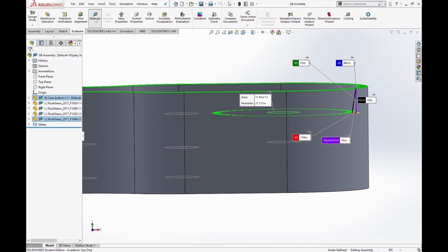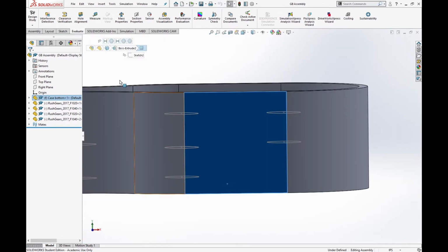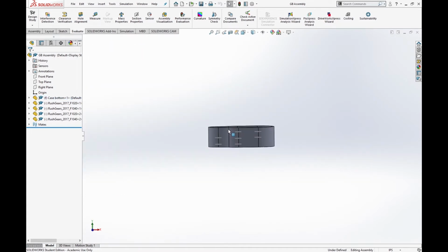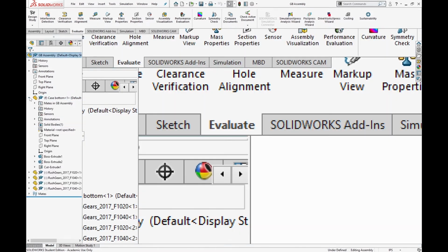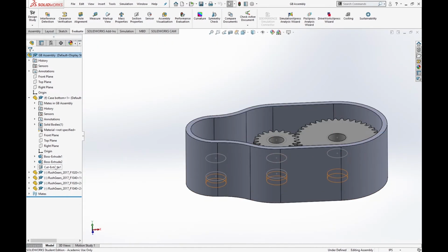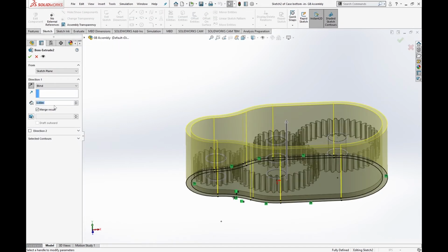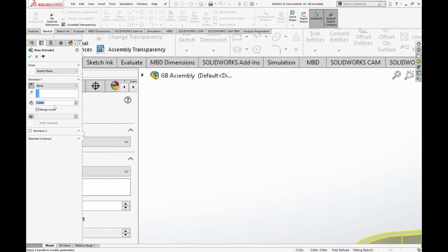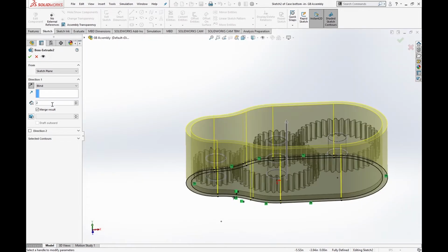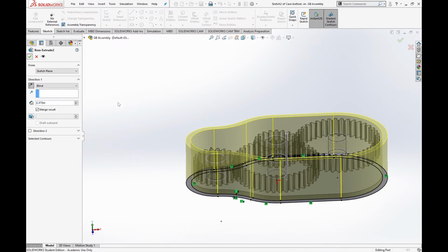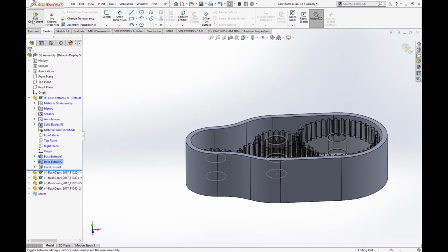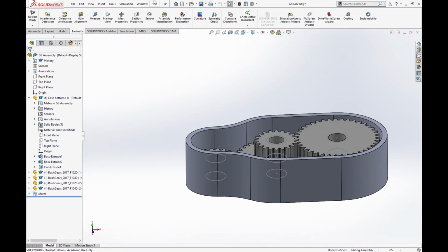So let's open up, I guess technically you don't have to open up that case. We can do that change from here. So it would be on this boss extrude. We're going to open up that boss extrude, and we had 3 inches. If we subtract the 0.625 from 3 inches, we get 2.375. So that's how thick this has to be. So 2.375, and then we hit enter, and we check mark it, and we exit edit component, and we save it just in case.